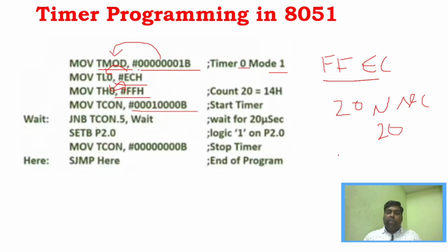that is, we are using timer 0, that is TR0. So whenever overflow happens, what will happen? TF0, this particular flag, will be set to 1, right? Whenever this is set to 1, the timer operation will be stopped, correct? Because the interrupt flag is enabled here. Now until it becomes 1, it has to perform the same looping operation. That is what is done here.